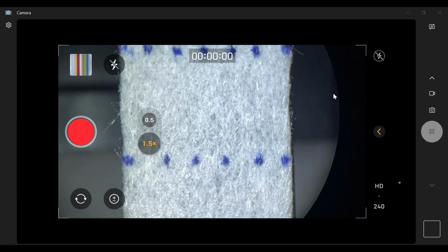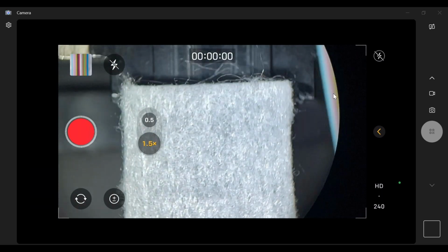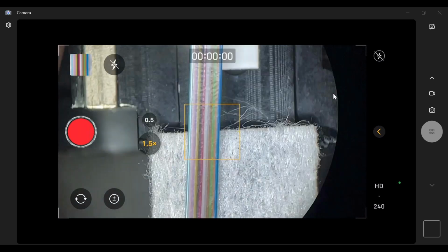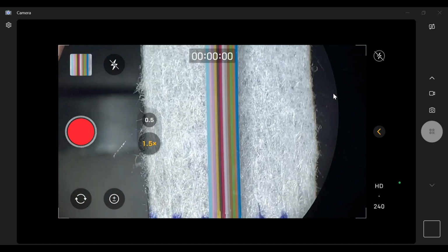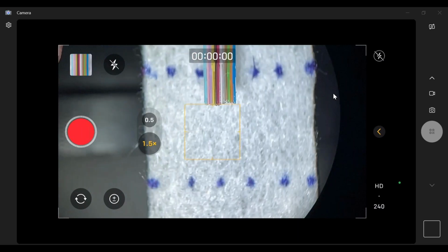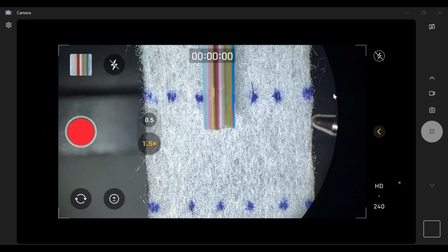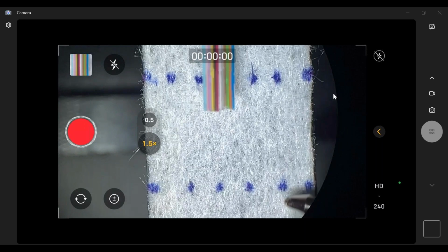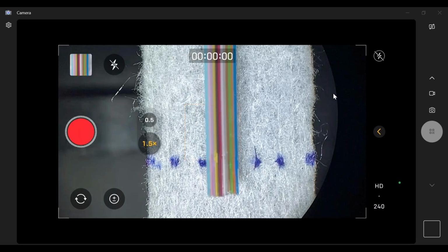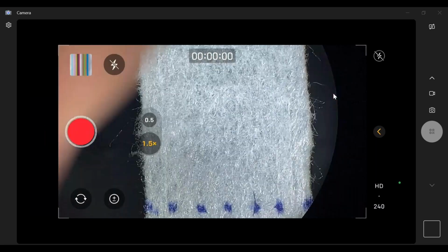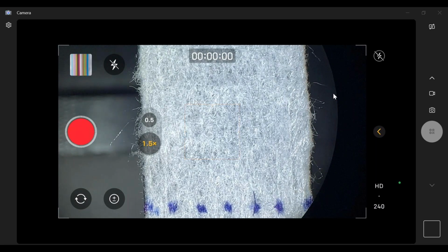So this first shows the marks on your pad, and I apologize for the color of this. It's a little cleaning white that we use, and I try to use a white background to give us a little bit of contrast so you can see it well. But again, this mark represents the shortest possible distance and longest possible distance. Now, this is the F870 12 fiber holder with traditional ribbon.